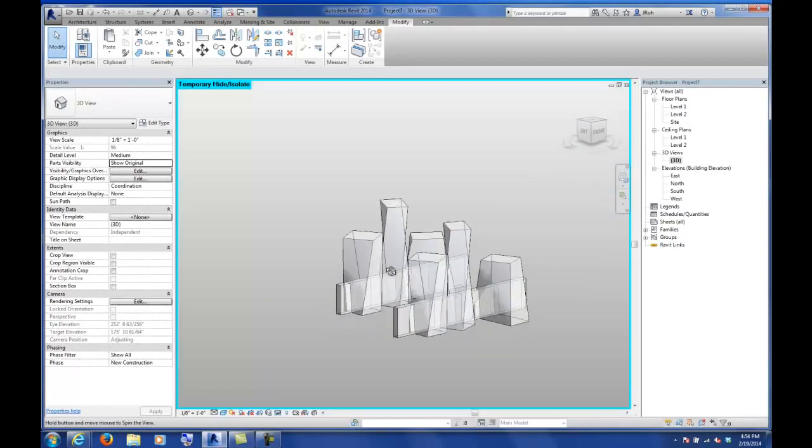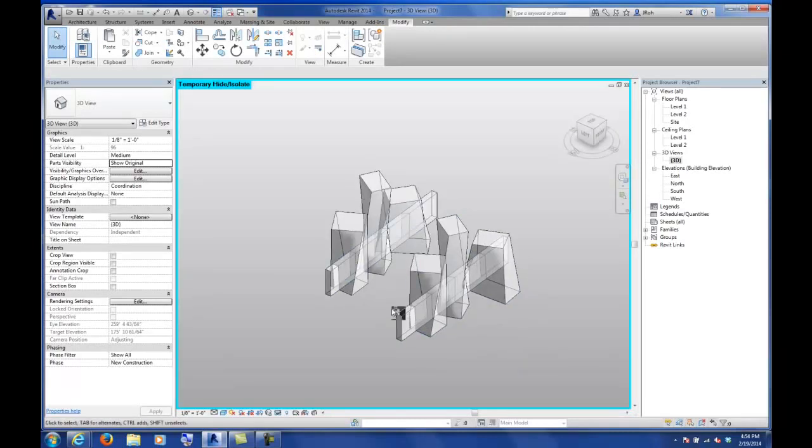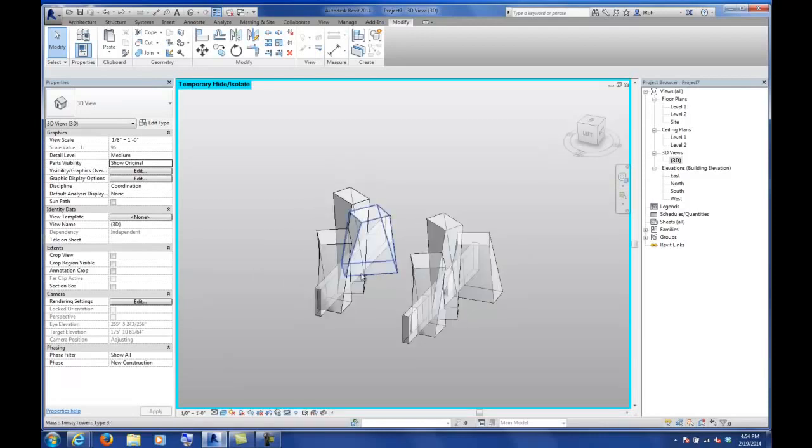Can you go over that cutting step again? That seems really useful. So in order to cut geometry, and yes, it is actually pretty nice. One thing that's hard to work with within the conceptual mass environment is the void. You draw the void, and then eventually it goes away, and you have to somehow find it to edit that particular object. The other way of working is you could actually make a solid element.